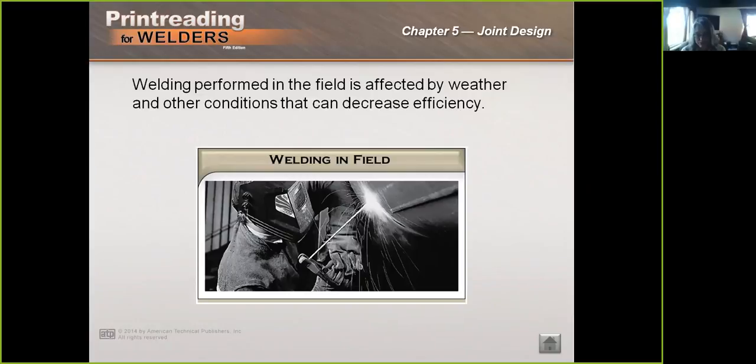We have no alternative. The pipeline right-of-way must be cut and graded for access by the pipe laying and welding equipment. The ditch is dug, the joints are strung for fit-up and welding. The sections of the pipe are lined up and welded in place to the required specifications. This activity actually requires highly skilled welders to work quickly in sometimes pretty uncomfortable conditions without compromising weld quality.